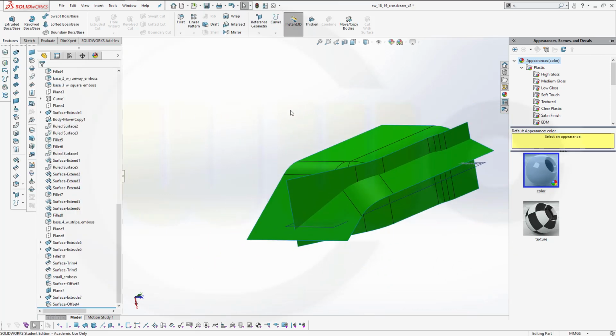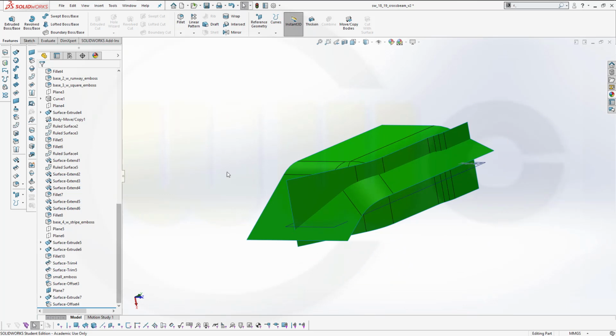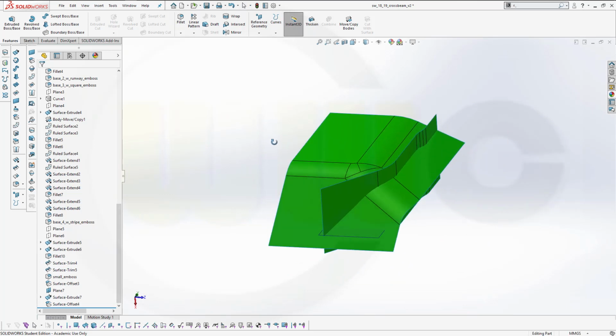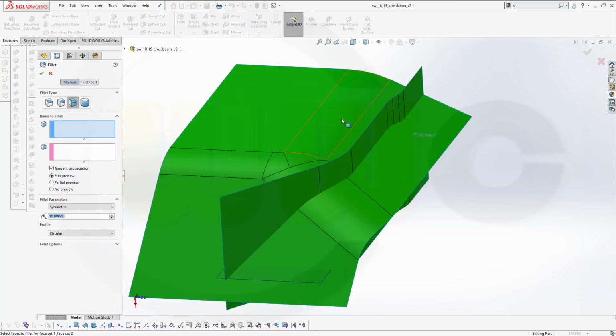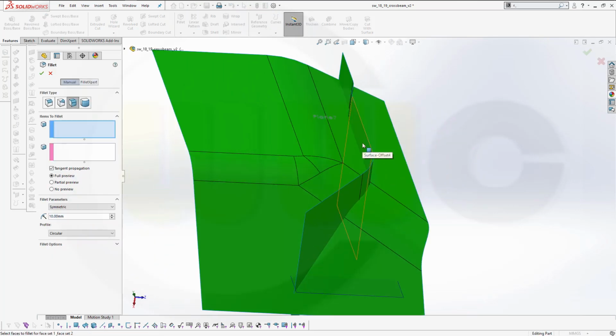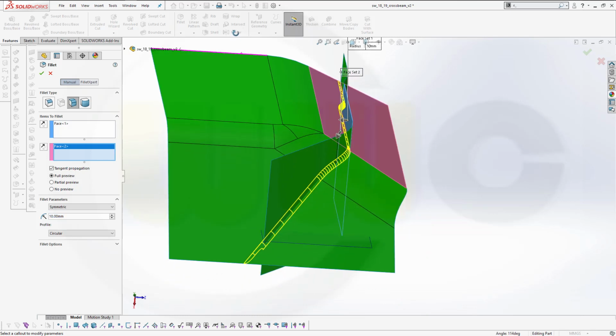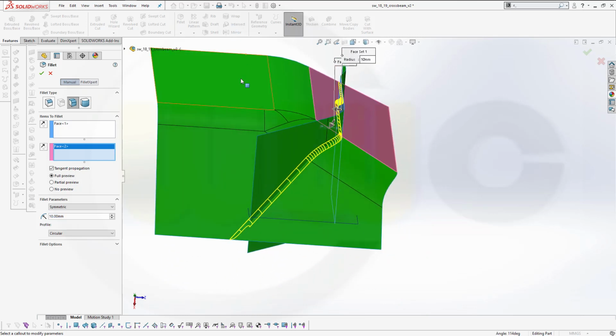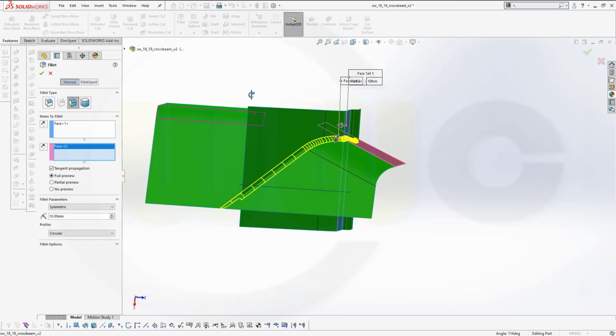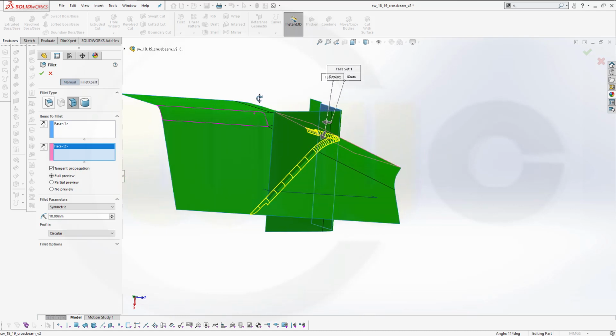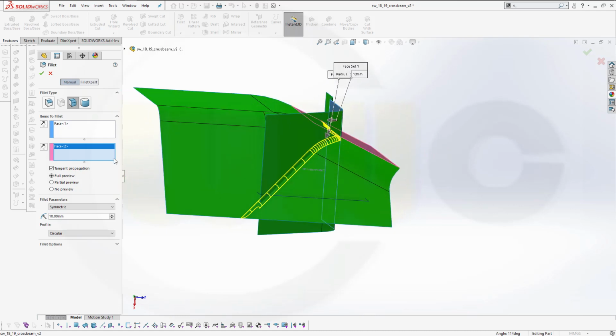Now let's trim these two. I could try a fillet, a 9 millimeter fillet. Let's see if it would work. I don't know. Let's try. I want to have a fillet between this face to that direction and this one, and that should go this looks okay. But I'm not quite sure, but it has to be 9mm.